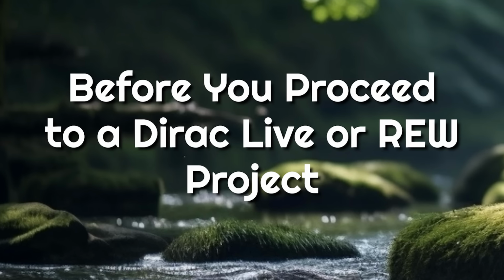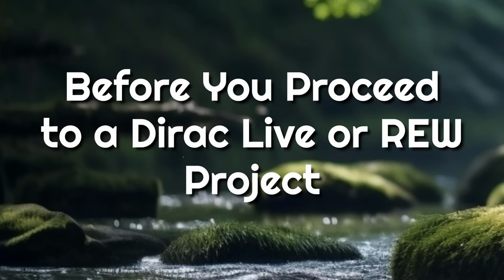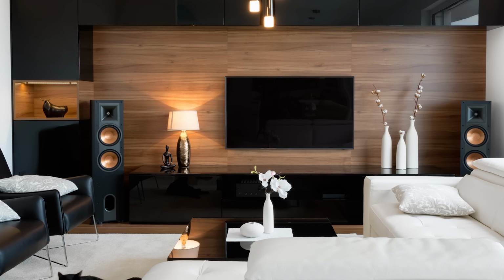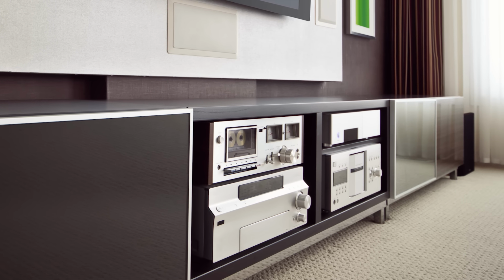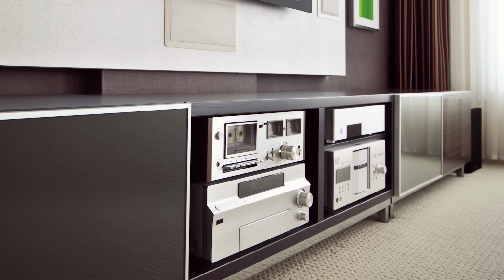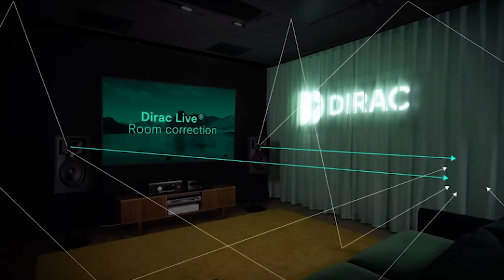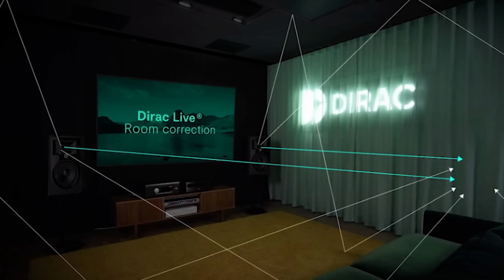Once you've completed these basic validation steps, your system should be performing to a high standard. Now it's time to do some critical listening and fine-tuning, such as relative levels and crossover points. As you make changes in Device Console, it's always good to validate what you think you're hearing with an REW frequency response sweep. Once you're comfortable with your settings and are seeing significant improvement in performance, it's time to consider a Dirac Live or REW equalization project.